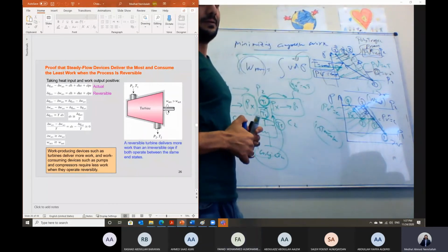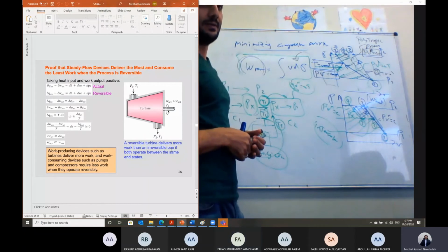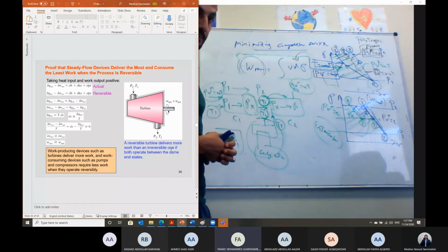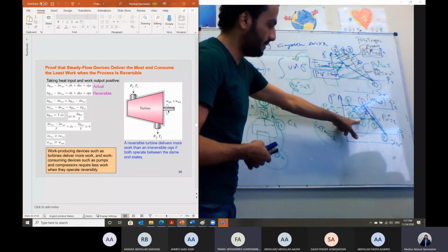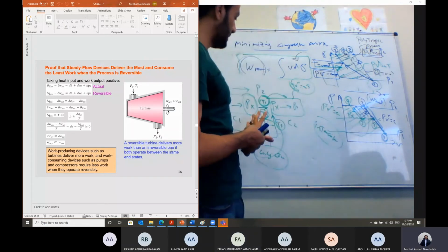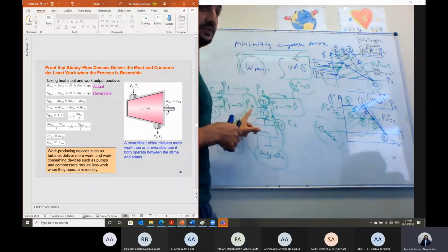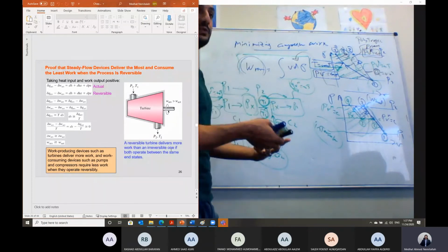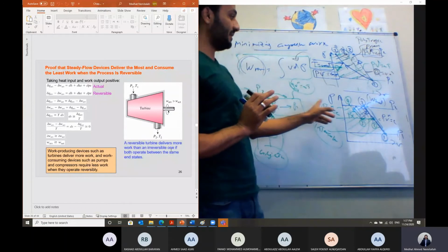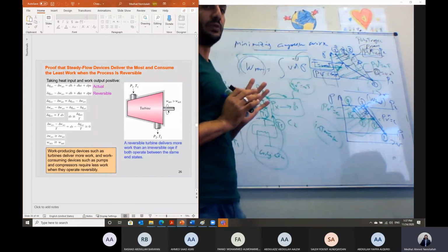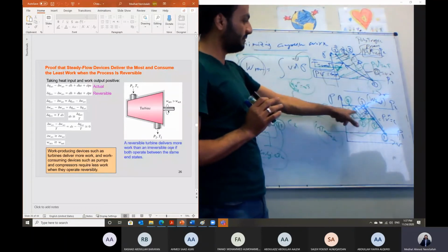Yes, but Doctor, if we reduce the temperature like the first one, aren't we doing the same process again? No difference. Reducing the process from 2 to 3? Yes. In this case, we have just to take the gases leaving the first compressor, cool it down using cooling water outside the compressor, and then take it to the second compressor, second stage of compression. Then it will be compressing from 3 to 4.